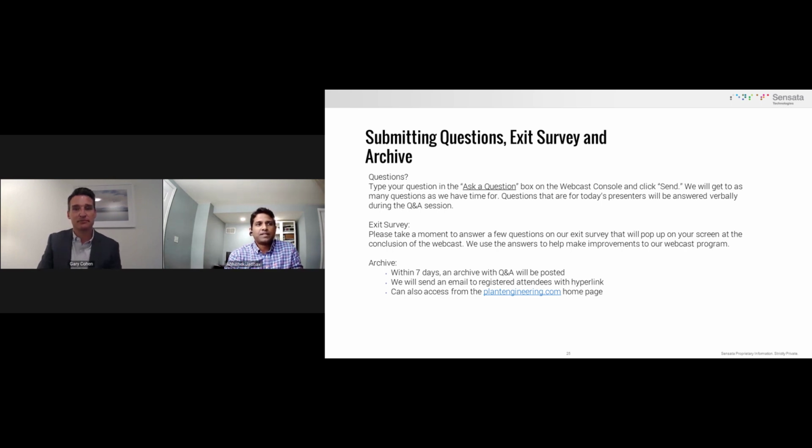Okay. To answer that question, the quick and short answer is yes. We will be looking at the secondary and tertiary failure modes. Our algorithms are trained, and it takes about 20 days for our algorithms to learn the asset. We go through the complete operational cycle and take more data points throughout that 20-day learning period. And any sort of deviation that may happen from that